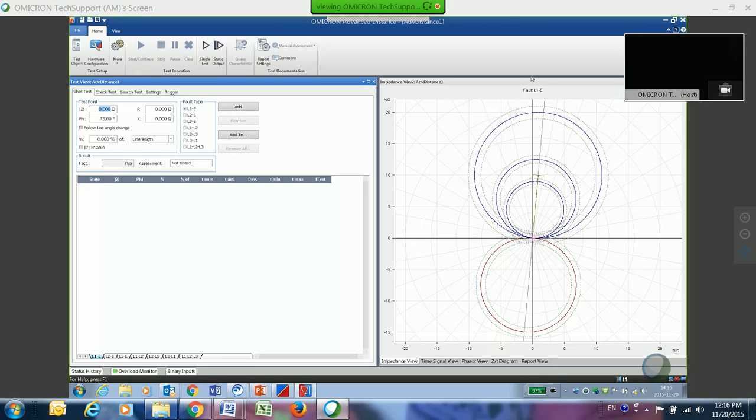And so if I was going back and looking at my zones, the 2 different modules that I was mentioning earlier were basically an advanced distance and a distance module. The advanced distance pretty much has the advantage of doing a search test, whereas just a regular distance module only allows me to do a shot. And so what that allows me is to come in here and place different shots. And they're just going to be different points that I can place on the diagram off to the right and actually be able to do certain tests within that one.